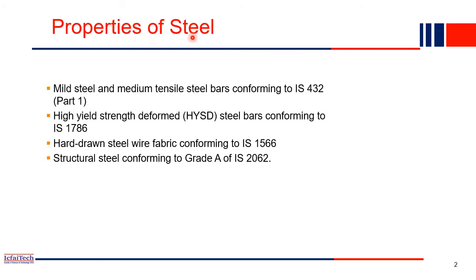We saw in the last lecture that the compressive strength of a concrete, if it is M20, is 20 MPa, 20 Newton per mm square, but the same concrete has a tension strength of hardly 2 MPa or 3 MPa. So that's why steel is extensively used to take care of the tensional force in a structure.